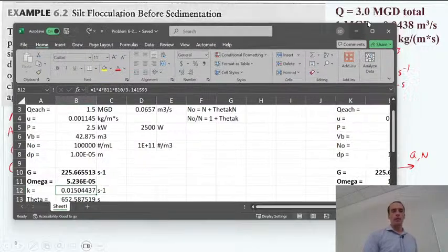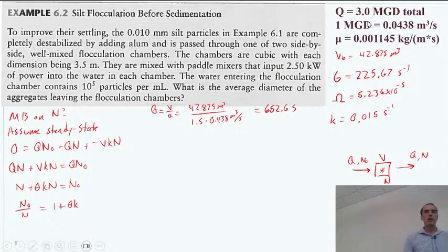And I kind of wrote that here to say, all right, well, what is this mass balance? We weren't given any information about the system being changed or faster, slower, anything weird. So we can kind of assume it's just going to be a steady state. That's a fair assumption. I went ahead and said, let's assume steady state so that we have no net accumulation. The thing is continuously flowing. It's kind of just going about its business. So then our mass balance would be 0 is what's coming in minus what's going out plus the reaction term.